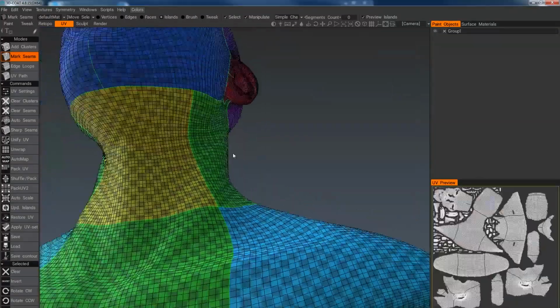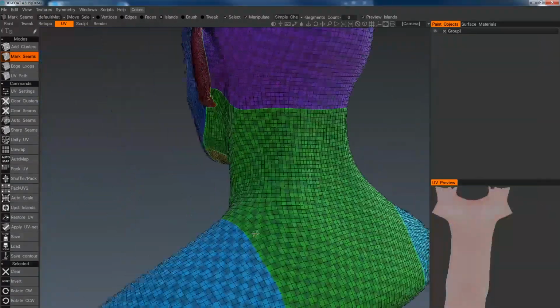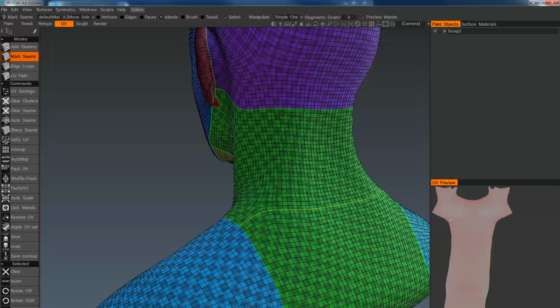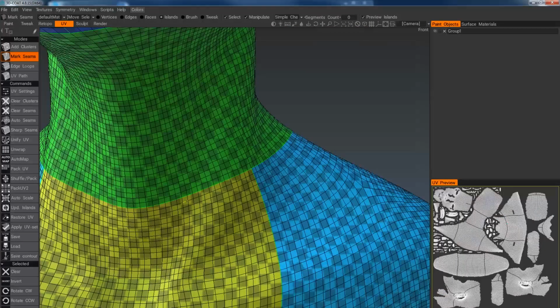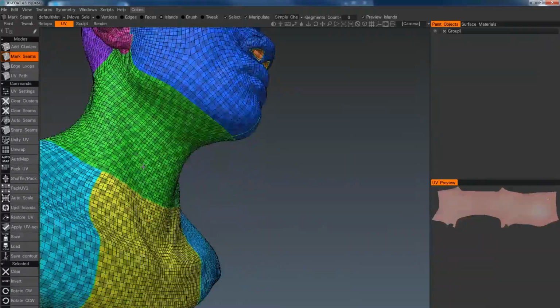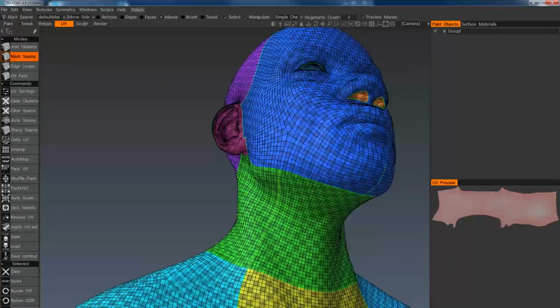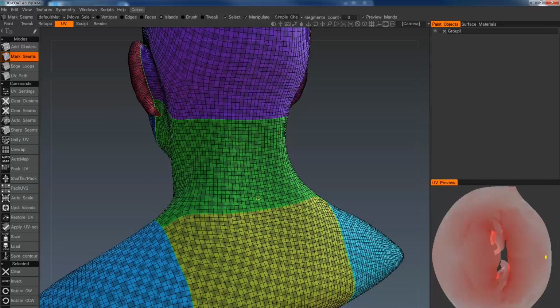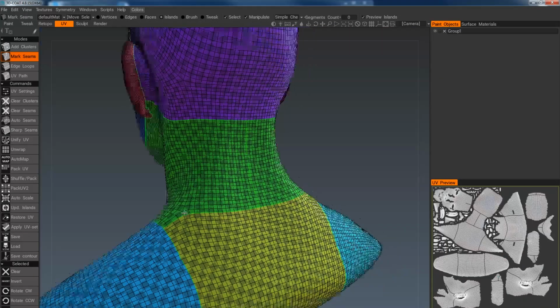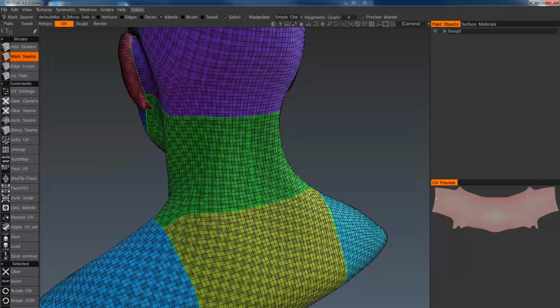Okay. This is terrible, so let's fix this. I'm just going to create an edge loop here. Clean this. Hope you guys are following along and it's not looking difficult. So let's see this. You see this? It's not unwrapping well. We have overlapping mesh, so we could just create one loop here. That will help the 3D program to open up this mesh and make it flat.